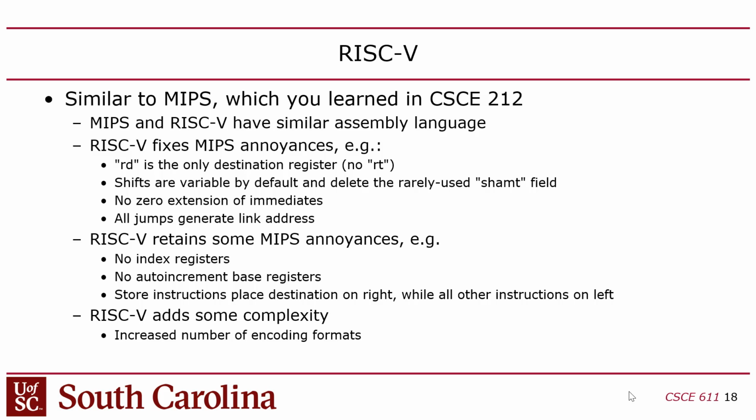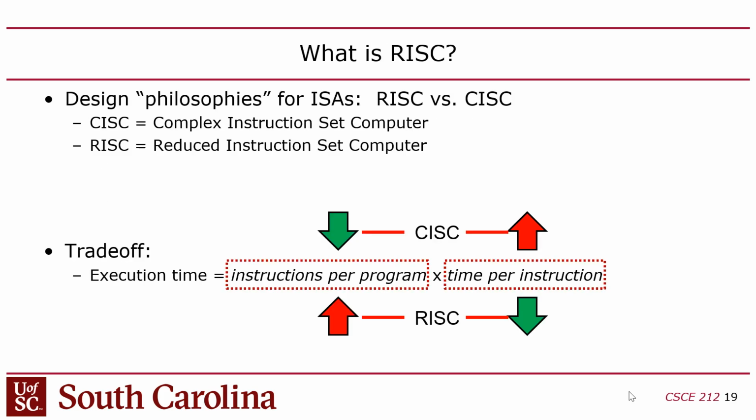However, if you're in this class and you're building an actual processor, now you have to care about that because you're going to have to design the hardware that interprets those instructions. So when we get to that part in the class, you're going to look at these U-type instructions and B-type instructions and be like, how, this is terrible. In fact, it's so confusing that I have to just give you the code for it because the way they shuffle is so arbitrary. MIPS tried to make it simple in the encoding format, but RISC-V just threw that away. But aside from that, everything is pretty simple.